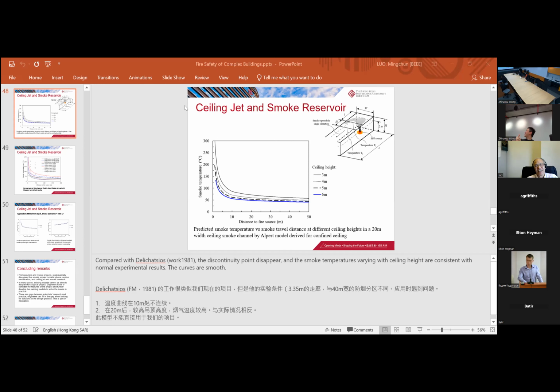There's a question from Audrey. Hi, Dr. Law. It's an amazing presentation. For example, when the plume fire models are applied to different national codes, they always involve some simplification, which makes a lot of difference compared to the Hasemi fire model. So I think it's a very good way to discuss the differences and give the constants to make the design more conservative.